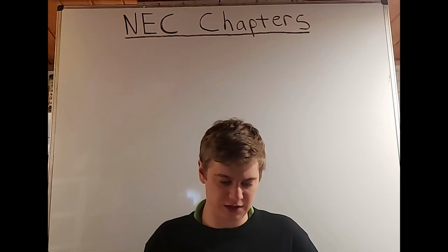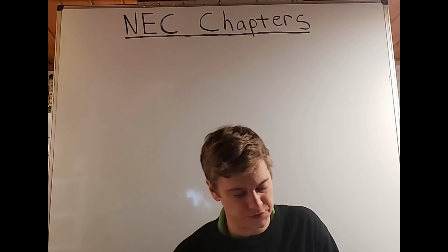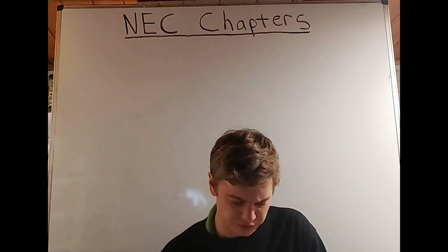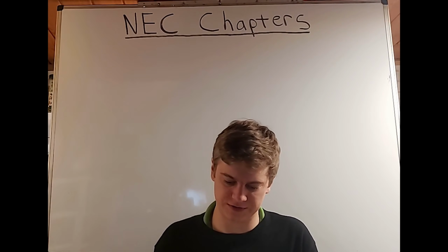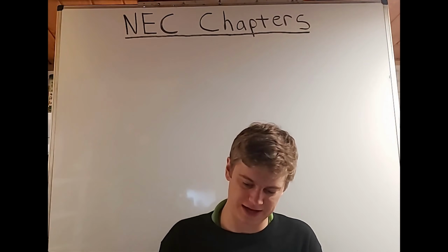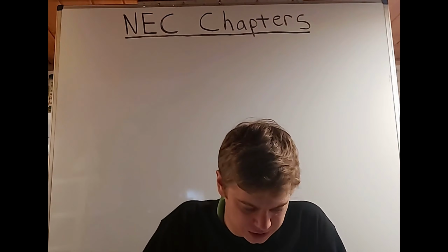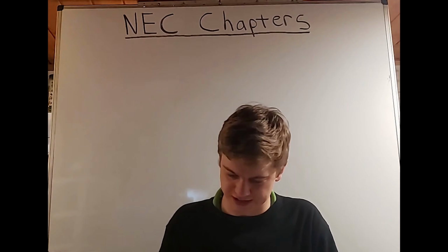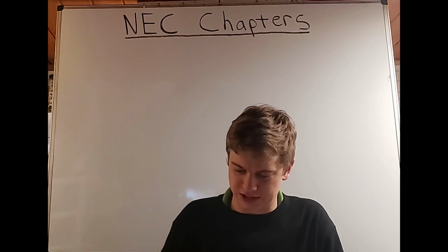Okay, and we see a lot of different types of cable here, and that goes all the way to Article 340, where we have the cable type UF. And then Article 342, we get into conduit types. That goes through Article 356 with type LFNC conduit. Then we get into Article 358, which then we have types of tubing. Tubing goes till Article 362, where then we have Article 366 auxiliary gutters.